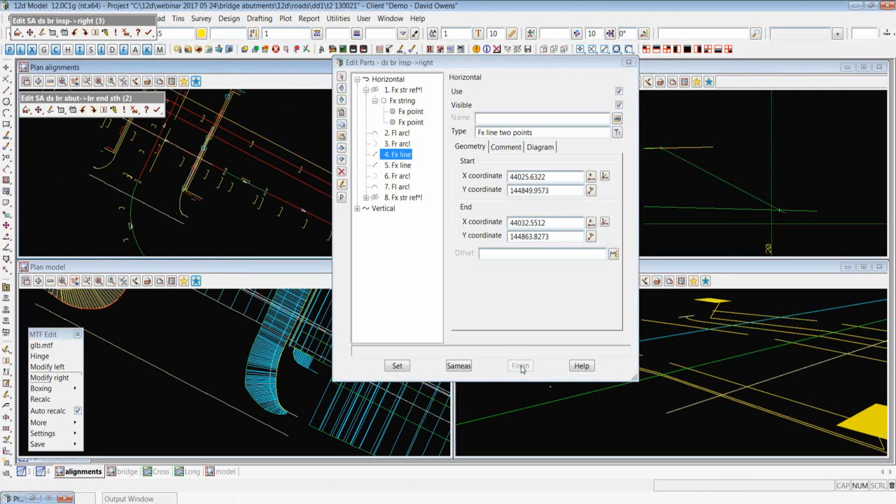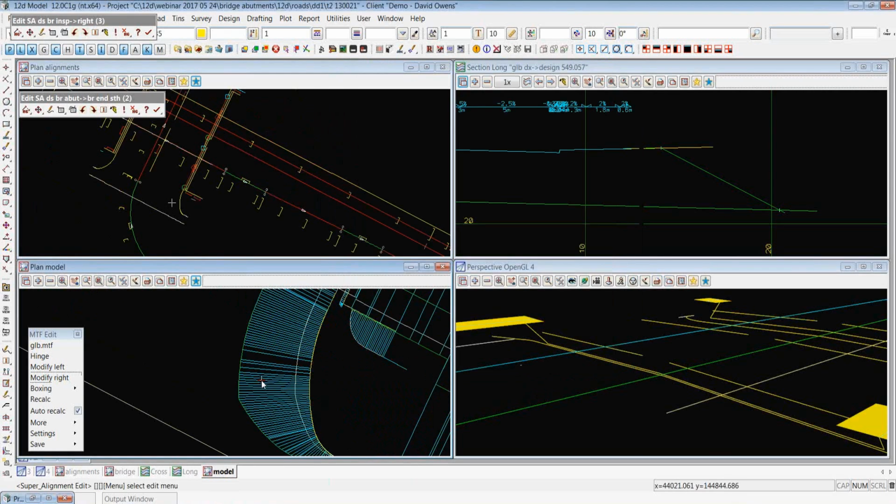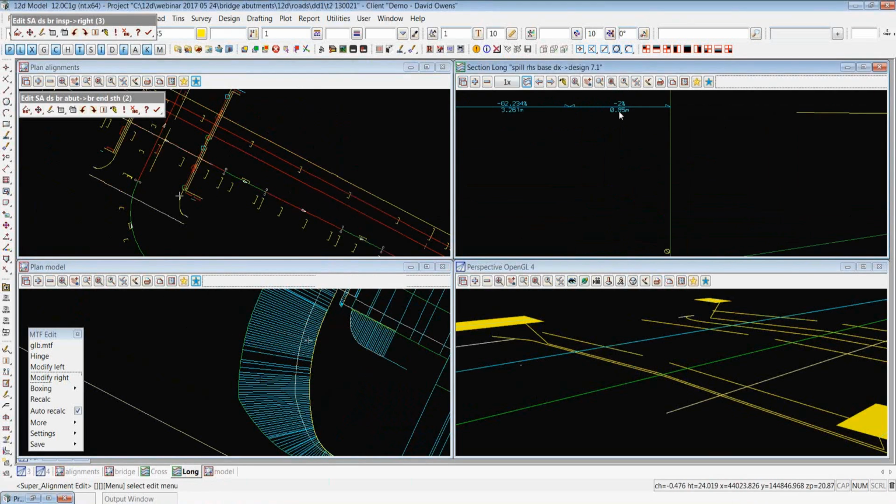So by breaking it into 2 functions and 2 alignments like this, the functions themselves are really quite simple. It's just a simple insert of a couple of links. So for the base part from the inspection level down, it was just a simple insert of the width of the inspection ledge at 850 mil, and then a batter down to another tin. And in this particular case, that tin is a realigned creek. So I've actually just constructed a sort of a platform to batter to down there of where the new creek is going to run, the levels it's going to have, but just a simple batter.